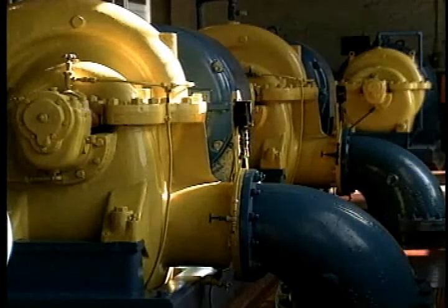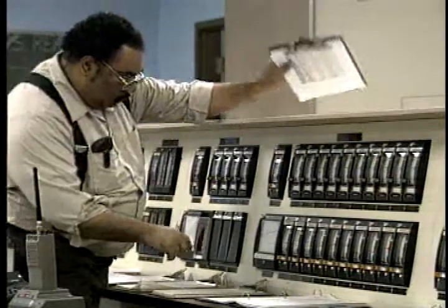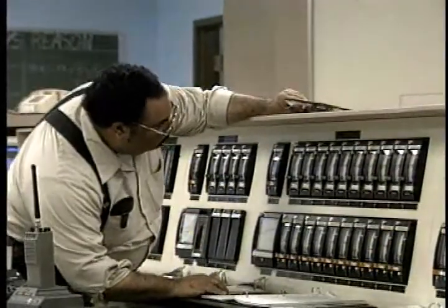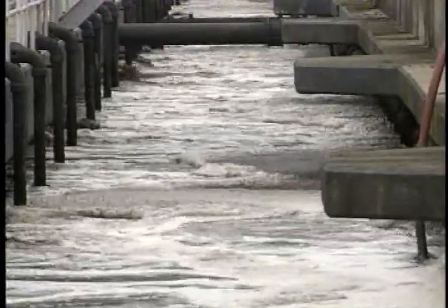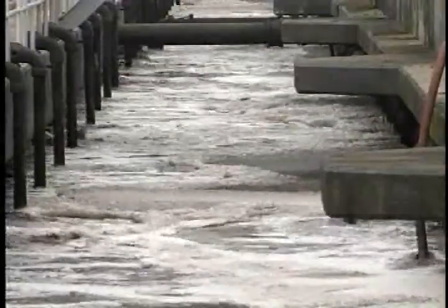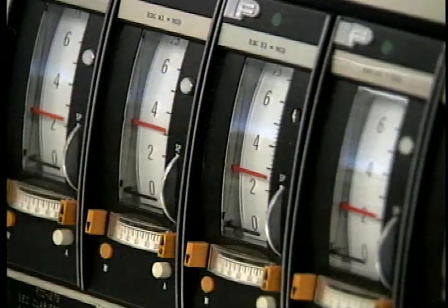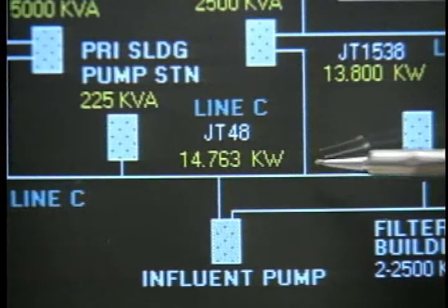Keeping centrifugal pumps working reliably as they move fluids from one place to another requires careful monitoring of their performance, usually over an extended period of time. When pumping conditions change or when a pump ages or wears out, the changes may be indicated by three factors: the pressure or head the pump produces, the flow through the pump and the piping, and the power the pump requires during its operation.